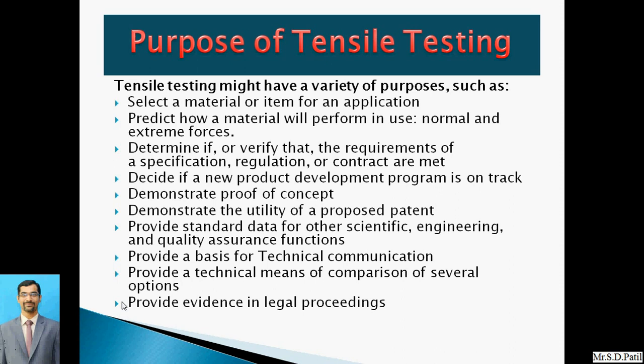So again, it is very important if some sort of sample testing is needed, whether we want it midway in any product development phase, when we want to check whether we are going with the good material selection or not, we have to conduct the tensile test. Then to demonstrate the proof of concept, whatever evidence is needed, whether it is achieving the exact strength or not, for that purpose also we need to conduct the tensile test.